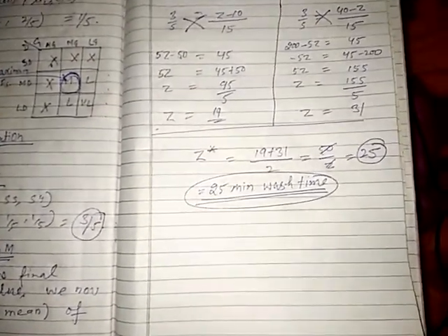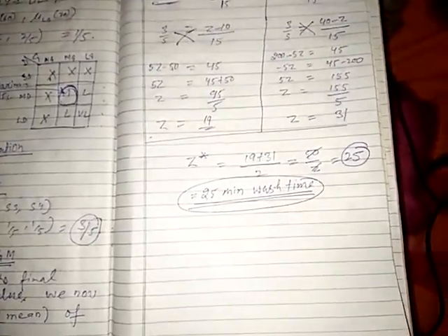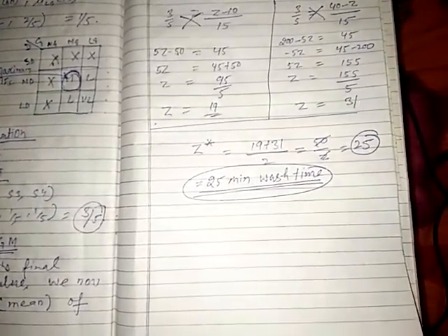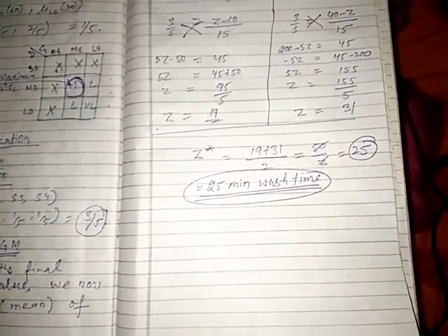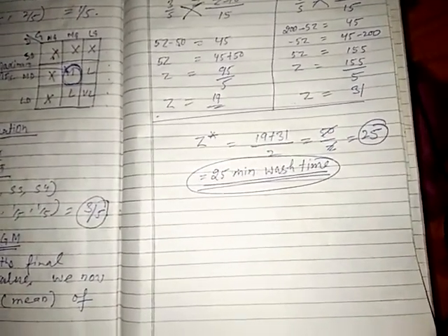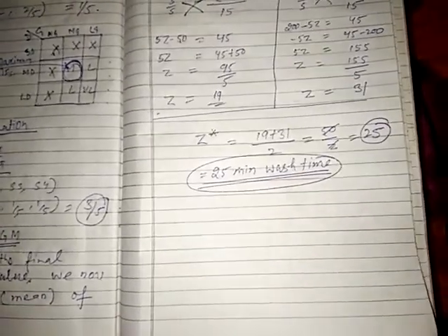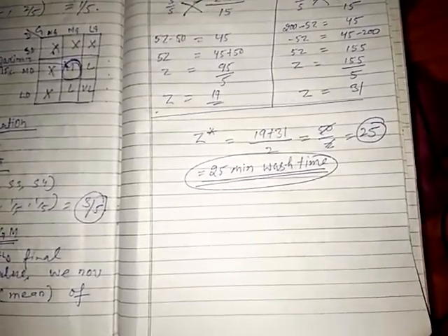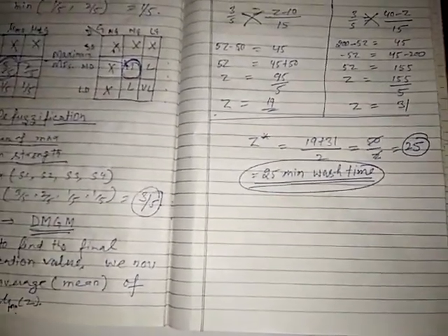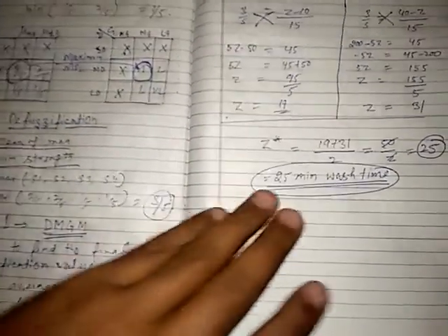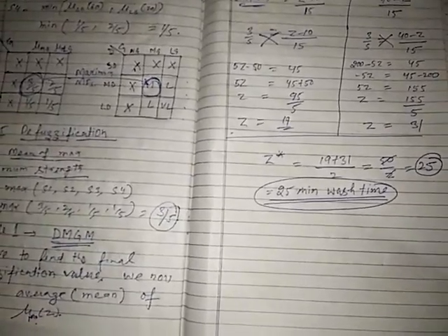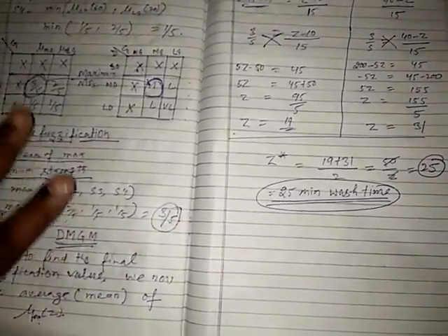That is all about that particular problem: we have to design a controller to determine the wash time of a domestic washing machine, assuming the inputs are dirt and grease, the input variables, and five descriptors for the output variable, derive the set of rules for the controller action and defuzzification, and the design should be supported by figures wherever possible. If the clothes are soiled to a large degree, the wash time will be more, and vice versa. How we calculate this value depends upon the defuzzification, and the time may vary because it depends upon your values and assumptions, but you have to include all the steps.